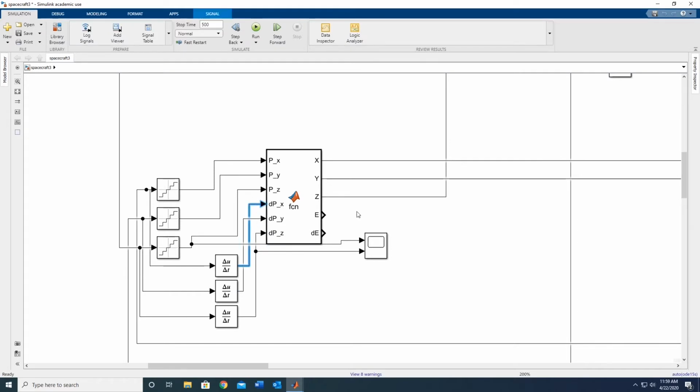All right. And then what I do here is I discretize the incoming signals so that they're in step format rather than continuous, and that just makes our integration slightly more robust so that we don't have to worry about minimum error deviations where we get these very tiny numbers and we're dividing by very close to 0 and stuff. And then all I do is I literally just take the derivative of each of those inputs to feed my derivatives, which are the same as velocity.